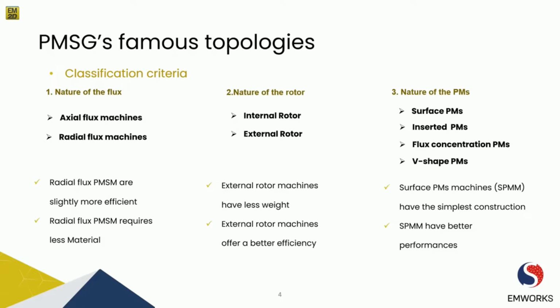They have the simplest design, but buried PMs are difficult to insert and cause greater torque ripples than surface PMSM. But the flux concentration helps to improve the performance of the overall generator, and we need to choose our design based on our requirement and the application.